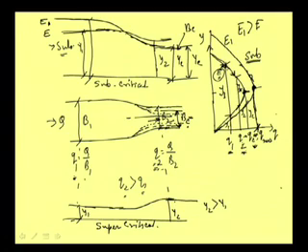But if we reduce the width up to a certain point, we can get critical depth. But if we reduce beyond that level, the depth here or flow condition there will remain critical, but the upstream side will be rising, that is, it will impound water in the upstream side, and that creates problems. Flow velocity here will be reducing, and then there may be flooding on the upstream, that afflux will create different types of problems. And if we want to avoid this sort of afflux, suppose in a city drainage system,